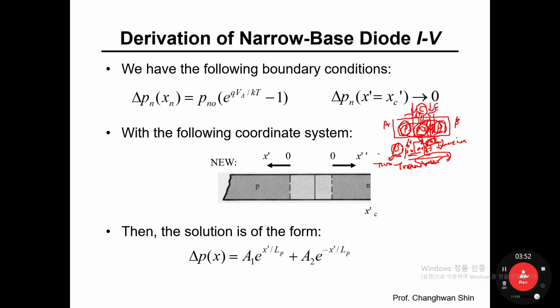This current flow is fully governed by how much recombination happens in the middle of the PNP system, so we can claim that the holes' movement is fully governed by the recombination event. This recombination event is explained by how much current flows into the N side.